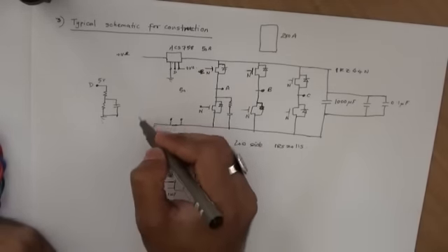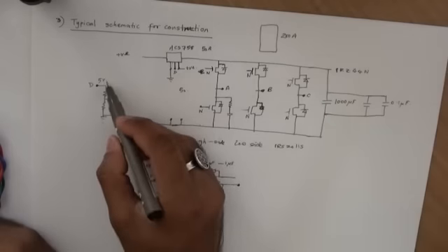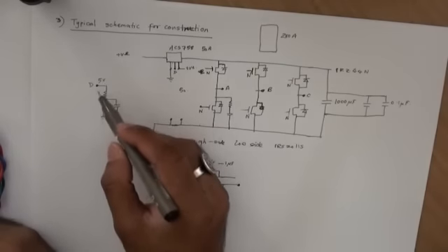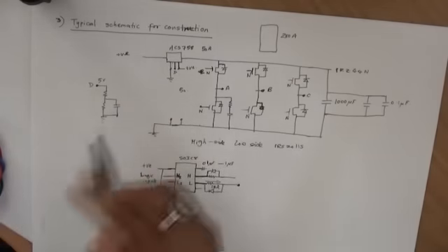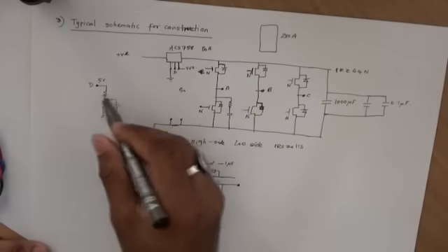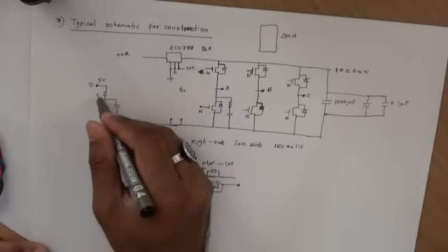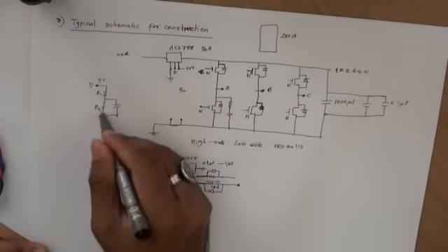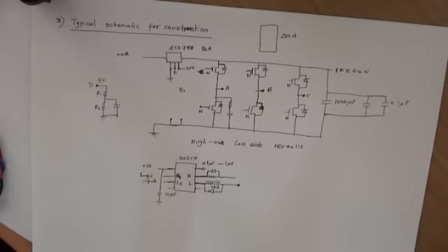So if your microcontroller ADC did not have a 5 volt capable input, then you want to have a voltage division made, and a simple R1, R2 resistor divider network will give you the adjusted voltage level that you desire.